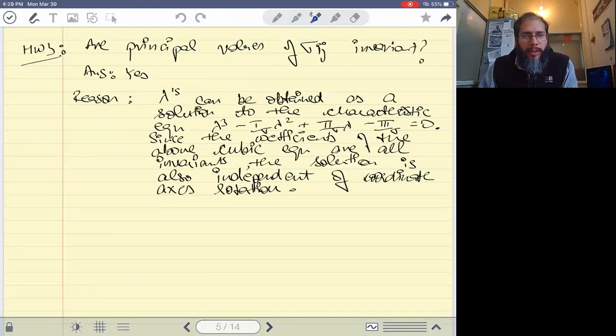It's quite intuitive, because one way to think about it is that if you rotate your coordinate system, there's only one coordinate system available where you have your principal coordinate system, and the corresponding sigma becomes nothing but a diagonal matrix with lambda 1, lambda 2, and lambda 3 as the 3 diagonal values. Okay, so that's just one special rotation of sigma. So you keep rotating your sigma until you find that principal plane. Okay, so that plane is distinct.